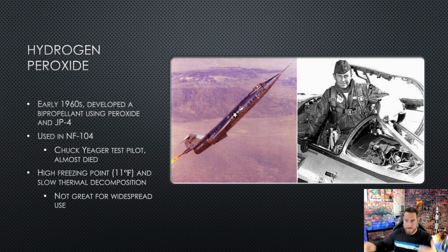So anyway, Yeager gets up there. He goes to fire the thrusters, but the thrusters don't work. Essentially, what happened is he got up at this angle right here. He was still low enough in the atmosphere that he had aerodynamic flow over the surfaces and still used the control surfaces, so he had good control authority there. The problem is, at that angle of attack, it cut off the airflow to the elevators, so if you pushed forward, it wasn't going to do anything, even though he still had airflow over the wings and everything.